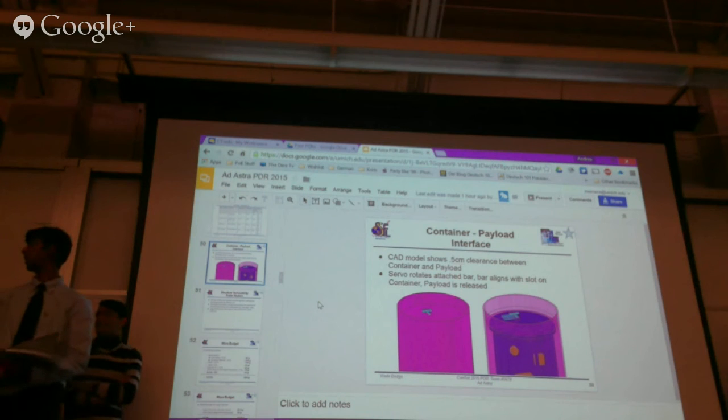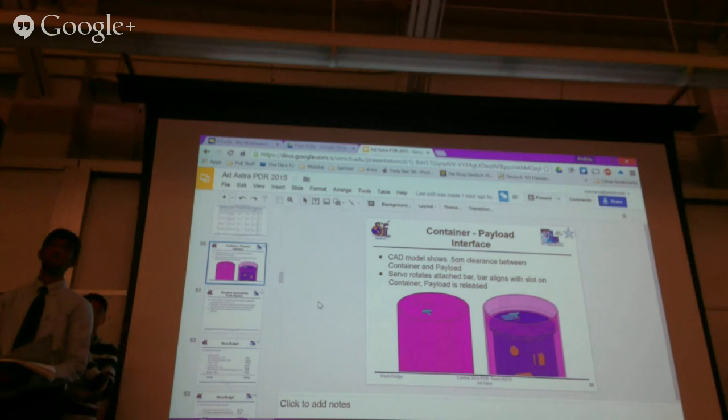So, right now we're still figuring out what we consider stable. And in the end, the code will have a way of, if it's getting too close to 300 meters, it'll just auto deploy. Stable doesn't really matter. But we'll probably look at the acceleration measurement and then see if it's falling straight down or if there's much wobble.